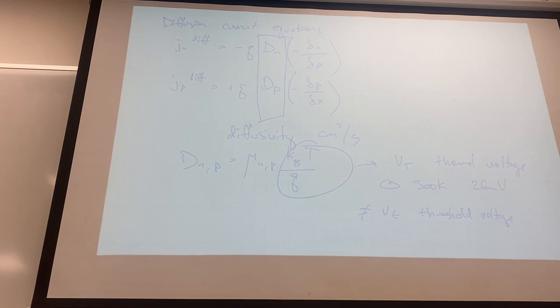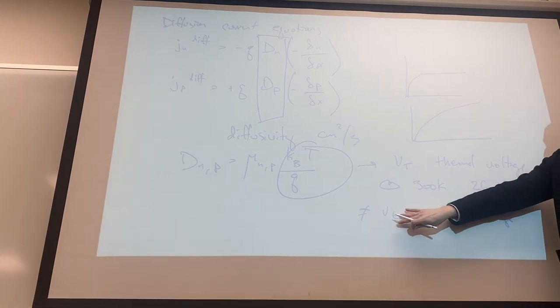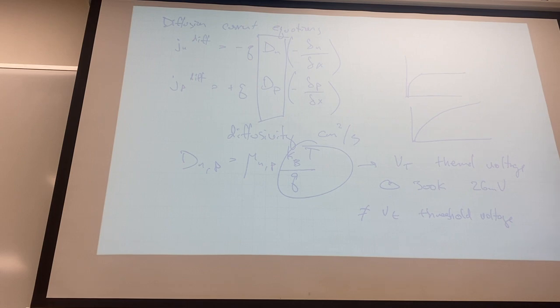And in small devices, in transistors that are really, really narrow width, the concept of threshold is a little softer. The device starts to sort of warm up and is starting to provide some gain. And then you pass the threshold voltage and then it's solidly in saturation, it's solidly on. And so the threshold isn't really a threshold, but more of a soft knee in the response curve. We go from having things that look like this to things that look more like this. You're like, well, where's the threshold point? Is it in here, I guess? But anyway, threshold, V sub little t, will show up a lot later on as well. Very different than the thermal voltage, but unless you're paying attention to subscripts and context, they'll be all over the place. Beware.